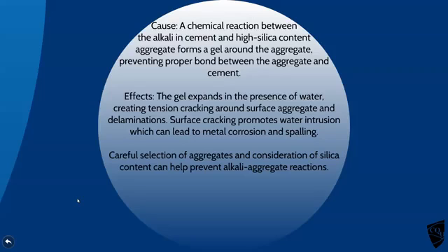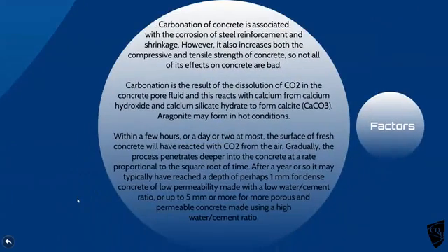Of course, the cracks allow the atmosphere and water to get deeper into the concrete, so there's no alkali barrier around the reinforcement anymore, and it will corrode. It corrodes, it expands, it blows off bits of concrete which spall. So you've got to be very careful you don't use what we would consider to be contaminated aggregates, to avoid the situation occurring. And then finally the carbonation one, which we're making.